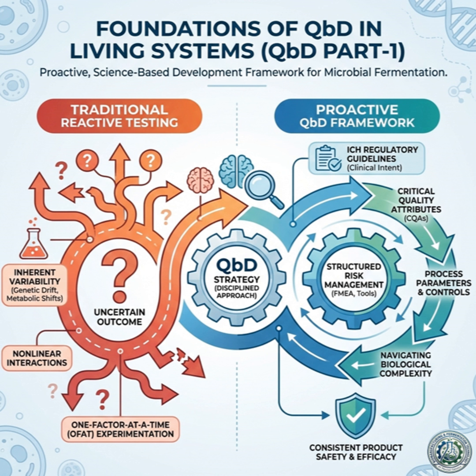It is a web. A web that gets even more complicated when you scale up. The scale-up trap. Yes, scale-dependent heterogeneity. Imagine a huge 20,000-liter tank. You can't mix that perfectly. So you have gradients, zones with high oxygen near the impeller, zones with low oxygen near the walls. So a single cell floating around is basically going on a roller coaster ride.